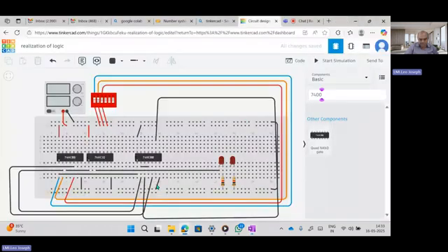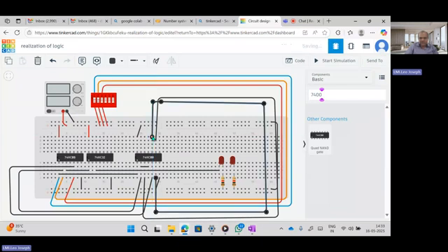Sixth pin to 10th pin means from the sixth pin, I am taking one more wire and doing the same thing. Here I am going from the top, this is 8, 9, and then I am connecting it to the 10th pin. So this is my 10th pin, and finally the 8th pin will be my final output. I am taking this wire like this, in the top right, not disturbing anything, and giving it to the anode of the LED.